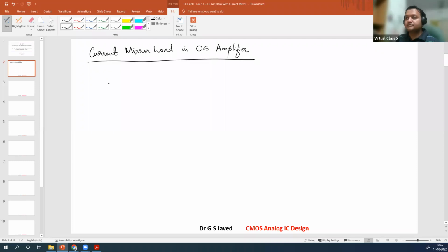look something like this. So you put a current source and you have an output resistance R0 in parallel to it with the supply VDD. You have an NMOS device with the source present, the supply input present on the gate.